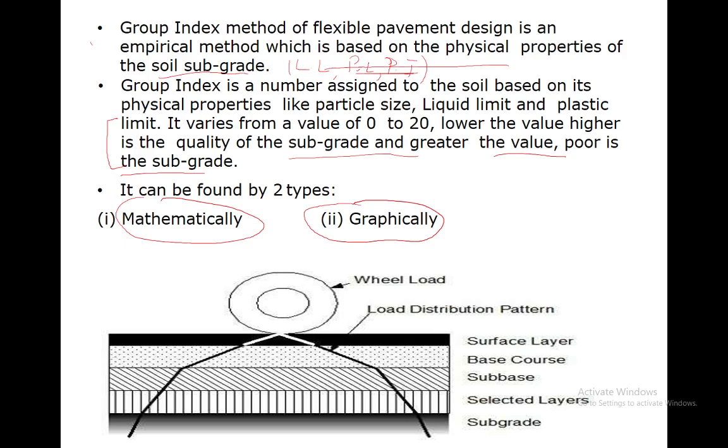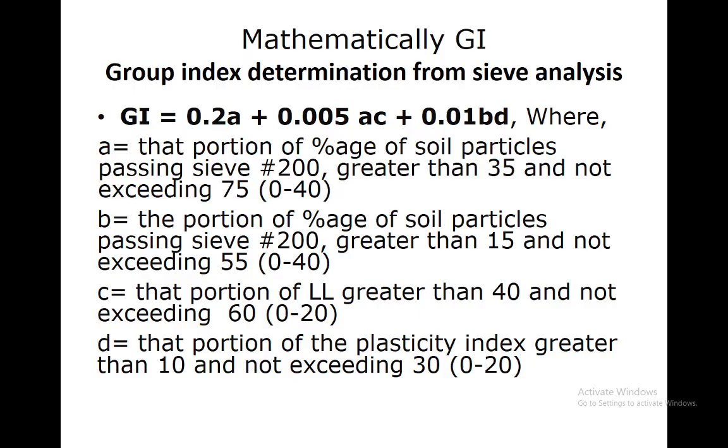If the supportive property of the subgrade is not according to the standard, there is a huge chance of deterioration in the pavement life before its designed life.